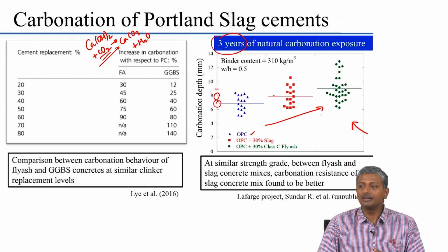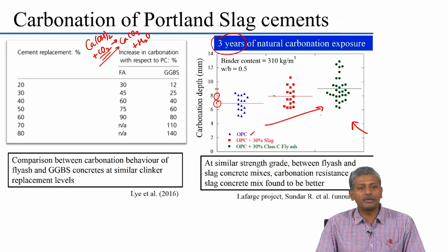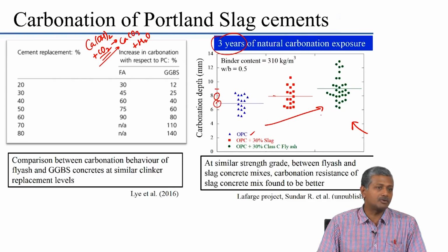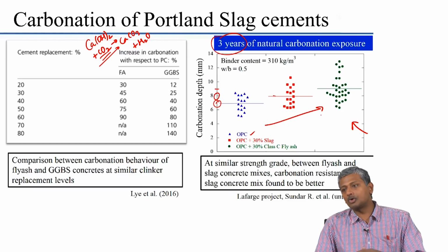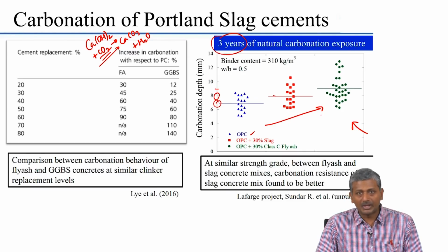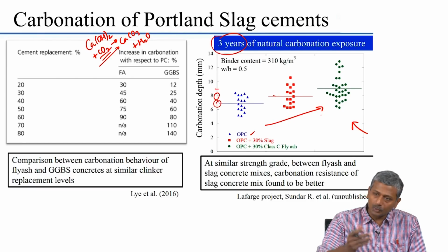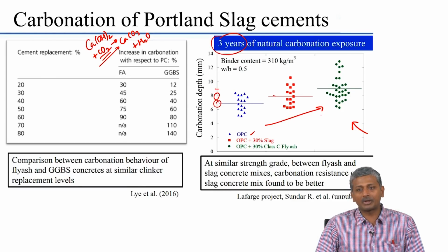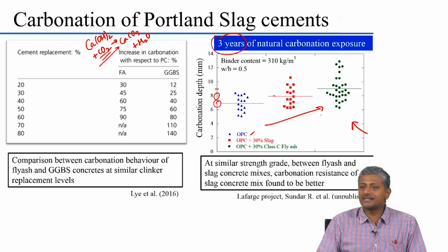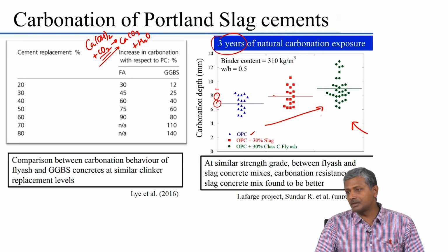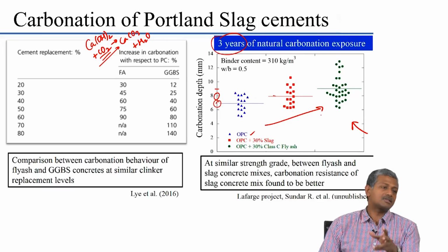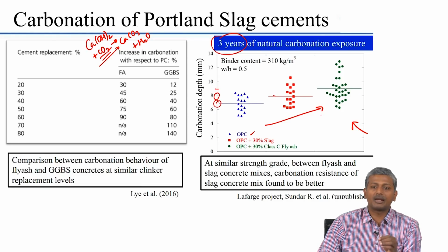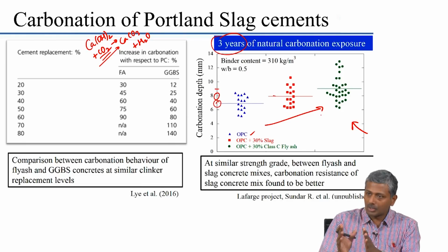Now, that is an important thing, because very many times if we take the rate of carbonation as an indicator of the possible damage you can expect in your system, then mineral admixture based concretes will always come out to be poor with respect to ordinary Portland cement based concrete. However, if you link carbonation to corrosion, that may still not be the case. Why do I say that? Because for the corrosion process to sustain itself, you need the presence of oxygen and moisture. And where are these coming from? These are again coming from the cover concrete, and if the cover is dense and impermeable like what we expect concretes with mineral admixtures to have, your moisture will still be limited to propagate that corrosion. So, all this is saying is that the risk for corrosion can be greater in the case of concretes with mineral admixtures in a highly carbonating environment, because more carbon dioxide penetration can happen.